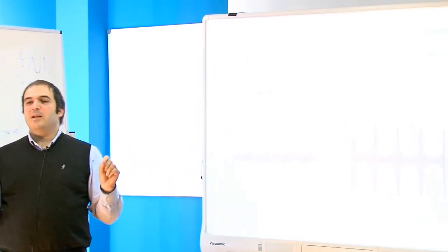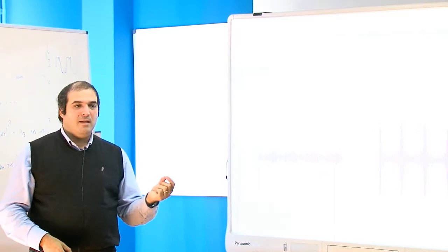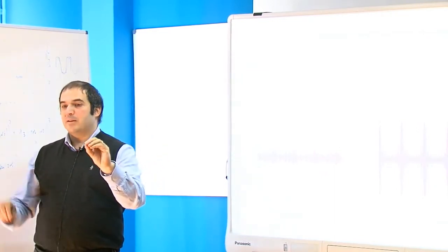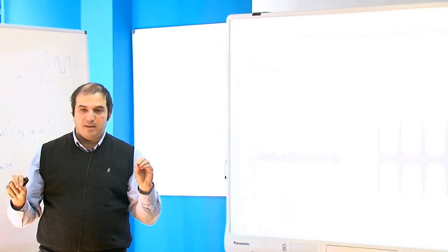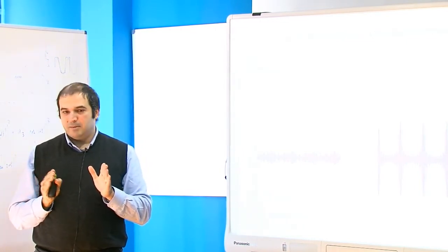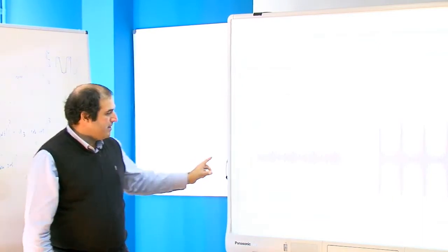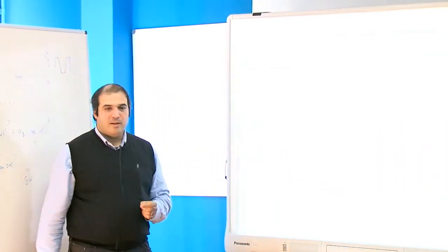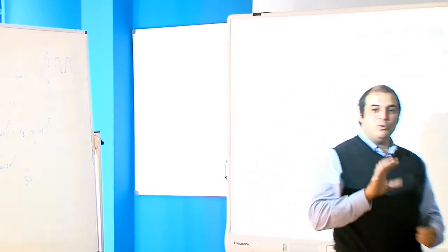You see? So that's why, in the beginning, I showed you white Gaussian noise and I showed you WCDMA, they seem similar, but the results were completely different. And this happens why? Because I forgot to look at something. When I look at the spectral analyzer, I'm looking only at the absolute value of the power. I'm not looking at the phase relationship. I'm only extracting the power of my device.